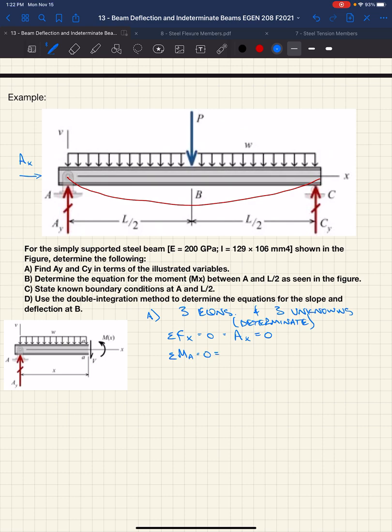So we've got a lot here, right? We've got our point load. Right-hand rule about A, it's twisting to the right, fingers pointing into the page, so it's negative. We have our point load P times its moment arm, which is L over 2, the distance from A to B. We have our uniform load. Well, our uniform load is going to have a resultant.